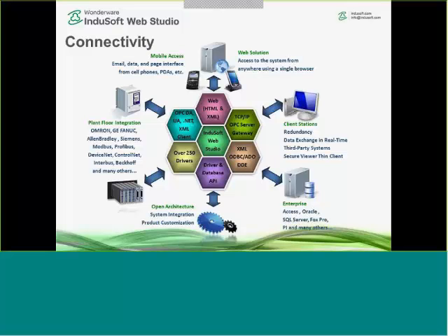And it also allows you to create applications where you create all the functionality of the application with multiple communication worksheets in the background. And then at installation, your field application guys, your field techs can configure the runtime application such that they say, oh, in this case, I want to communicate with Allen Bradley PLCs or possibly Schneider Electric PLCs, Beckhoff, Omron, the list goes on and on. You can develop your application and make it so flexible that at the development level, it's already accounted for, and those changes can be made very easily in the field.